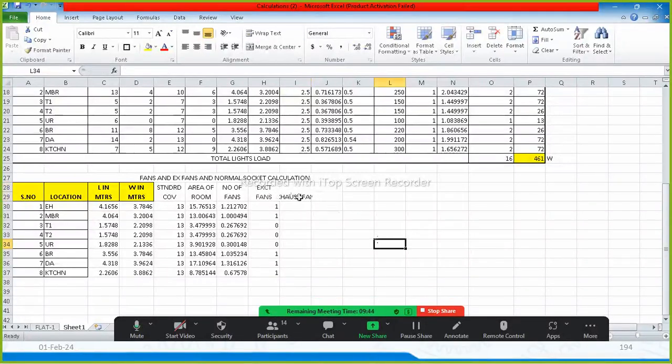When it comes to exhaust fan, as I told you, with the help of that calculator, for a residential building we don't do those calculations. I'll give that Excel sheet also. But if it's a commercial building, based upon the volume, because if you're going to software companies and malls, we have a bigger toilet area. At that time, we need to calculate exactly based upon that Excel sheet. But here, as it's a residential building, I'm taking an assumption of 1.